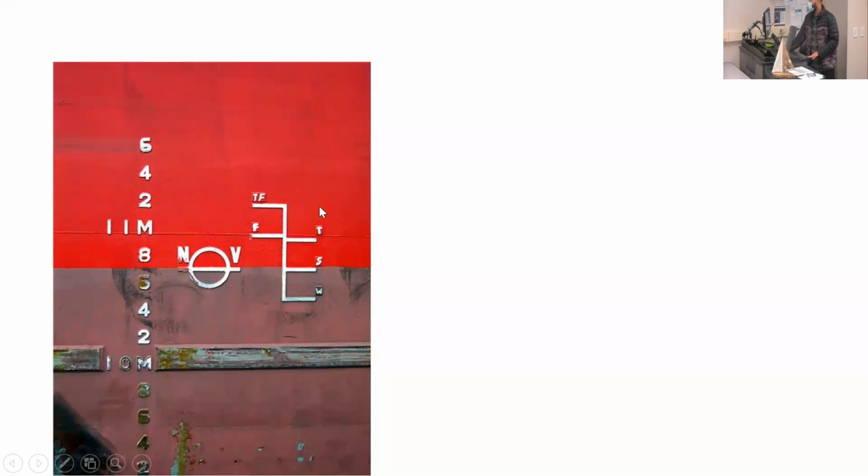If you didn't take this into consideration and say you loaded up to the maximum level here, starting from New England, as you sail to the tropics, the water line will keep going up and your hull might hit the seabed in shallow waters, okay? So it's to prevent all of that from happening.